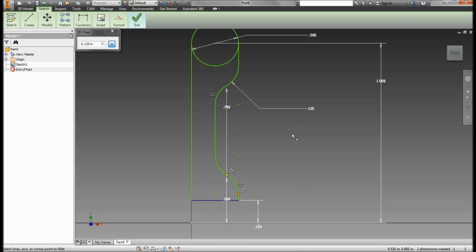That TYP stands for typical, meaning typically that's the size of these radiuses that are on this type of geometry. So it doesn't have to be exact, but we're just going to go ahead and edit my dimensions to 0.0625. And I always tend to forget things when I'm working on this stuff. So that actually, oops, yeah, that's right.